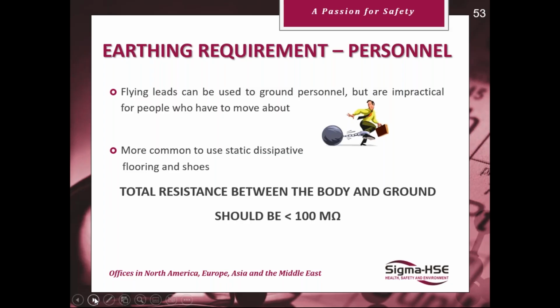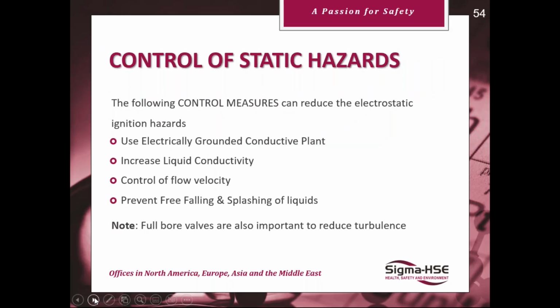Don't forget, if you're using static dissipative mats, these must be earthed. And check your floors, as I said before, to see if you can get away with using this method of earthing. These types of measures can reduce electrostatic ignition hazards.